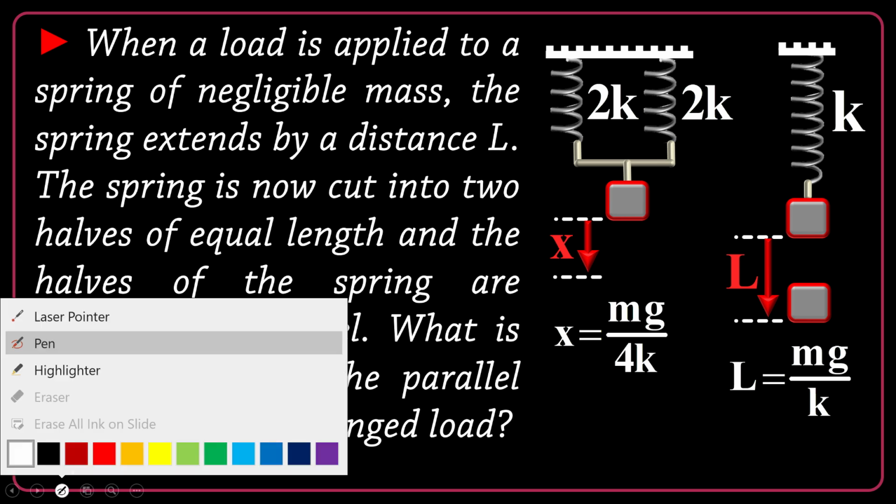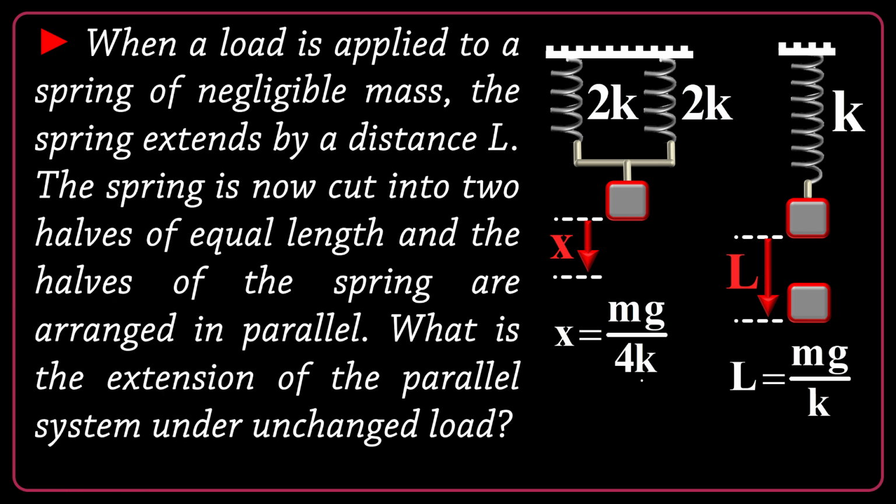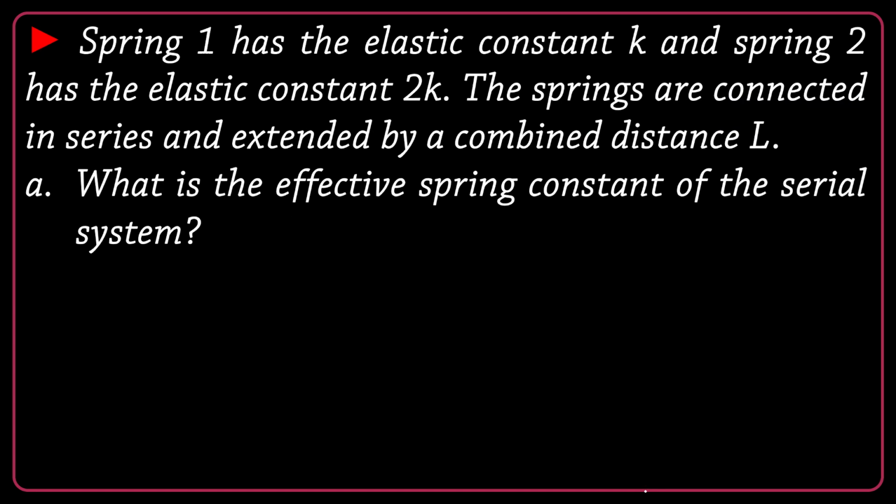Let me change the color of my pen. Okay, mg over k here is exactly the L. So x is going to be L divided by 4. So extension under the same load will be a quarter of the previous extension. Okay, let's continue for another example.